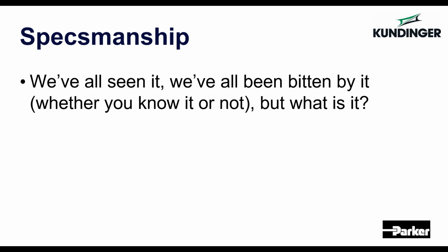So we have all of the specifications in our catalog from a max perspective will get you about 2,540 kilometers of life. How much that is in your application depends on your speeds and your duty cycles. But it's always important for us to sort of do the math and see what 2,540 actually means in your application. And sometimes you'll be surprised how long that can actually get you. And in some applications, that's nowhere near enough. So we need to start looking at going under what catalog ratings can say.